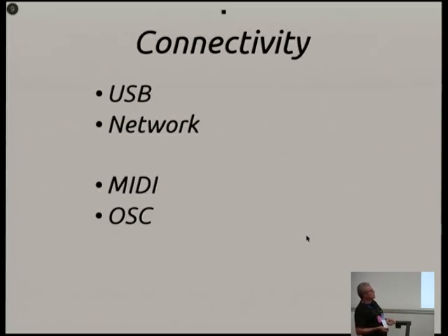And the two equivalent technologies that map to those are MIDI and Open Sound Control. MIDI is traditionally a serial port type-based protocol, but most MIDI adapters now are USB adapters. And the MIDI spec does actually have a proper USB device class in it. And then Open Sound Control is pretty much Ethernet-based UDP packets over the network, can work over wireless, can do pretty much anything. We're not really trying to do proper music playback, it's more control. So we're not worried about 10 millisecond latencies. It can be a little bit slower.